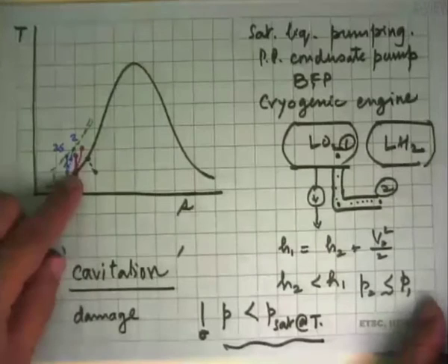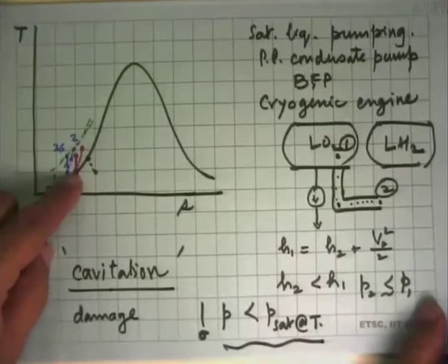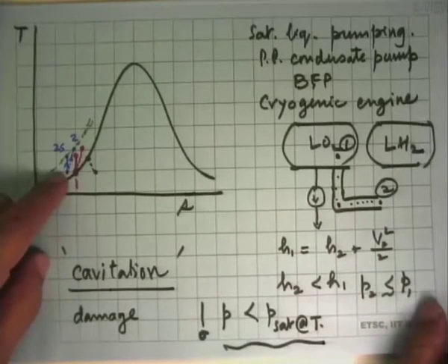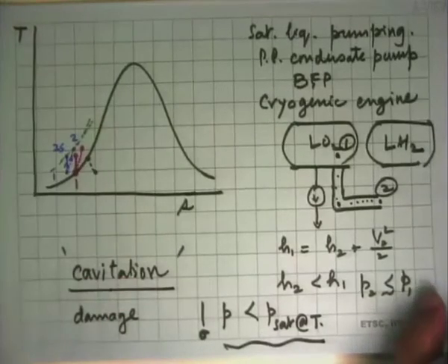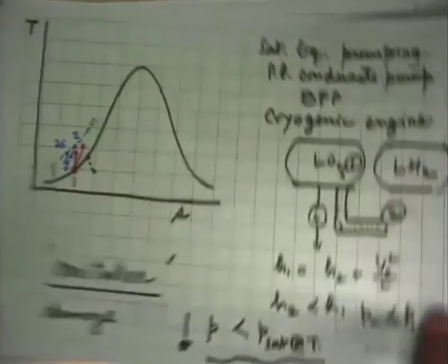Okay, so pumps will always start either in the saturated liquid state and go up, or in the compressed liquid state and go up, but never in the wet region. Again, we handle only a single phase. Okay, so this is about pumps.